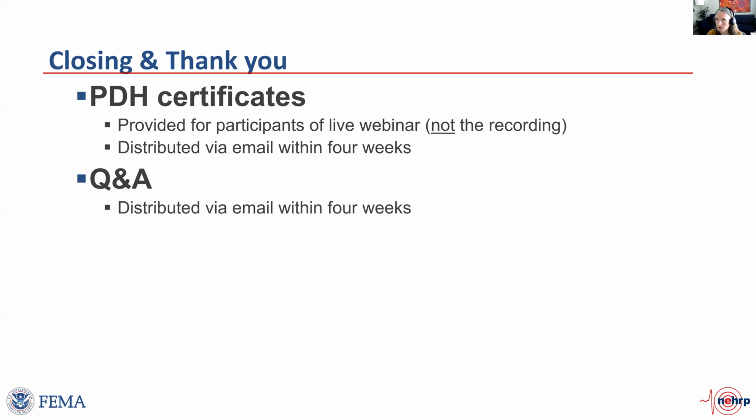So is there anything you can comment about why you would want to use the modal analysis? In what particular cases you'd want to be using it, understanding the findings from P-2012. And there's also been a couple questions about the limitations on using ELF for buildings of a certain height. It says above 48 meters, and whether there's any anticipated change coming out of the P-2012 findings that might affect the ability to use it for taller buildings.